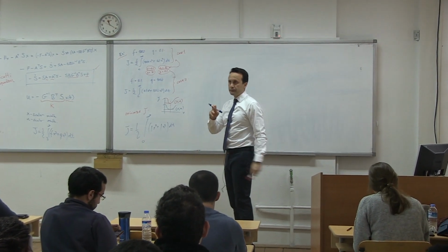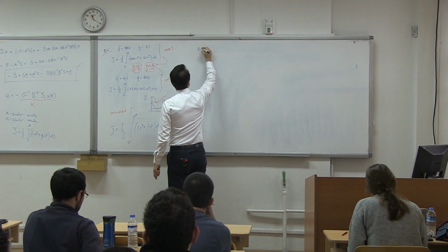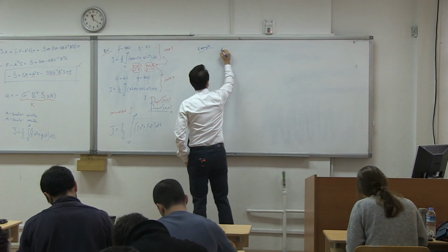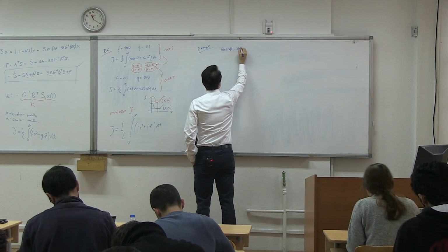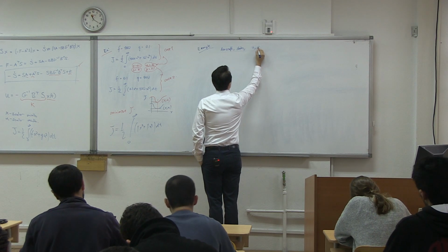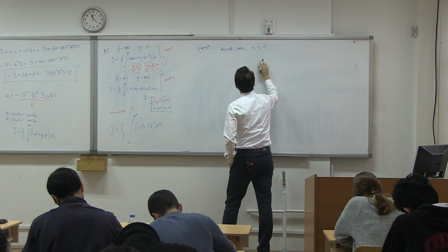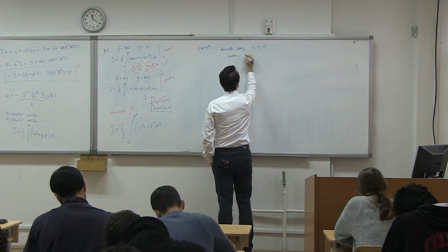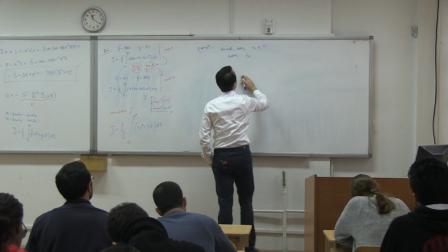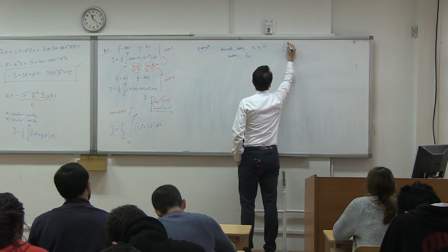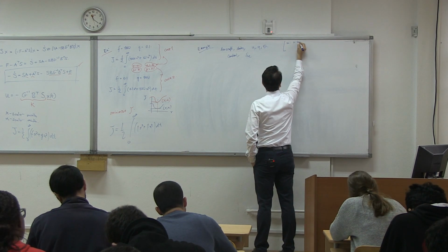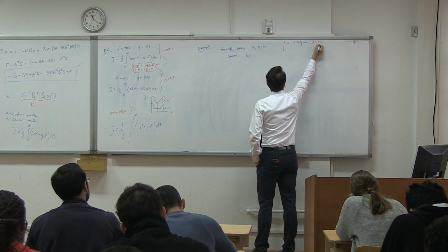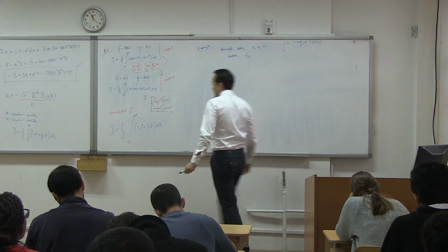Let's look at the matrix situation. Okay? Let's give an example. I'm not going to solve it, but just to set up the problem. Let's say we have an aircraft with states u, q, and theta. Okay? And control, let's say I have a one-dimensional control, and control is the elevator. And u is x body velocity, and it's in, I don't know, feet per second. Let's make it meter per second, so we are in SI units.